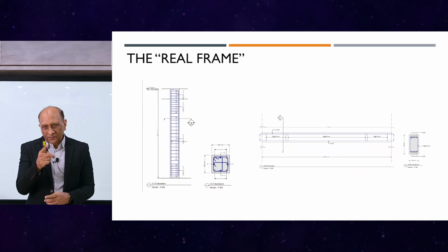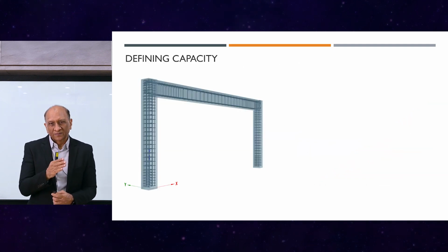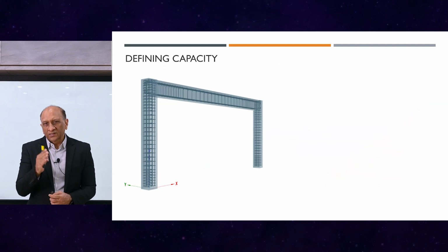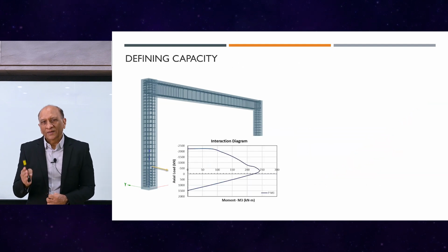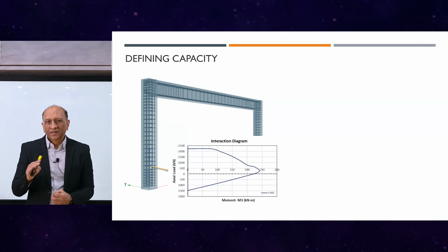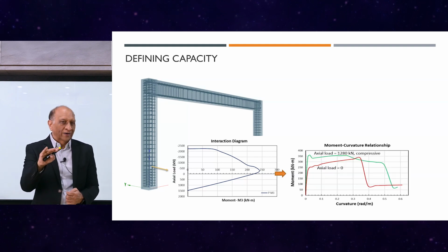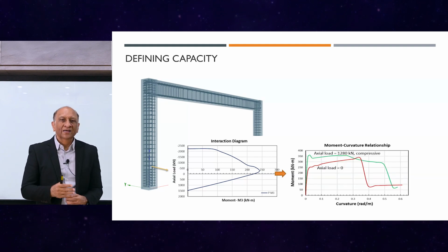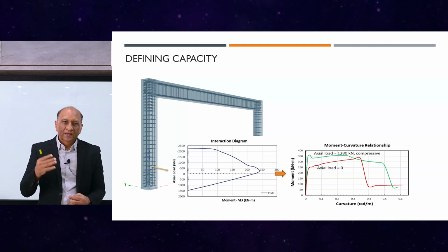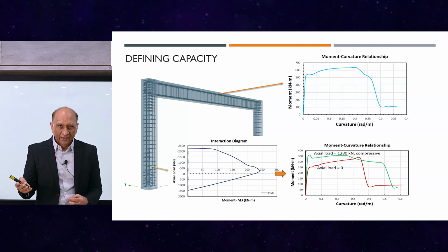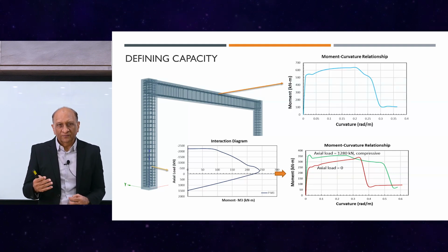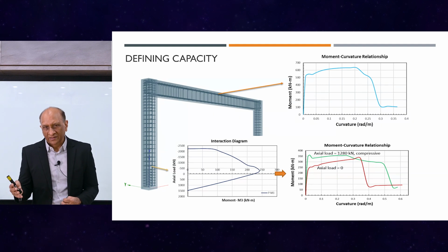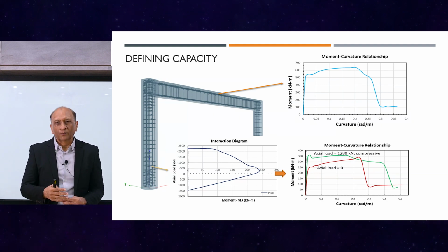And then you can see now, the important thing to note here is the displacement versus force values. So if you put the service level displacement, let's say 0.5% drift, which is typical for a service level, you get a force factor, let's say of 1. Whatever force that is, we call that 1, which is just before yielding. If I increase that to the 2% drift, which is the design maximum level drift, you get a force level of about 3.